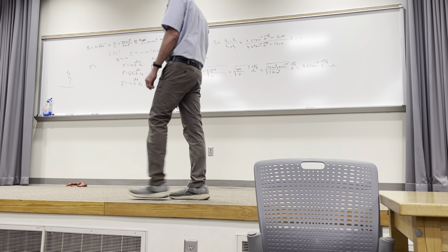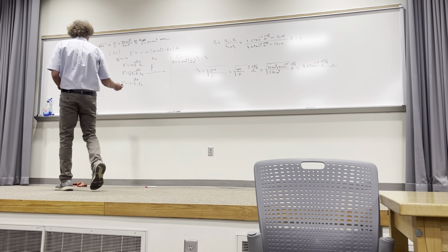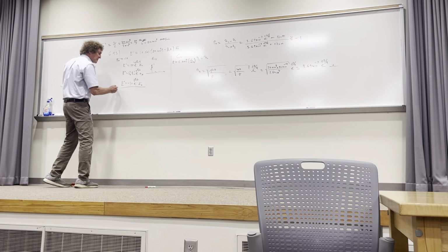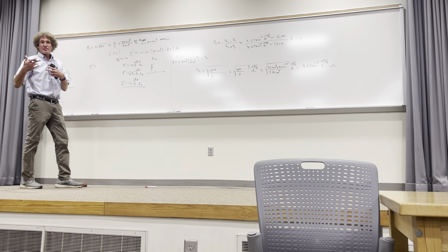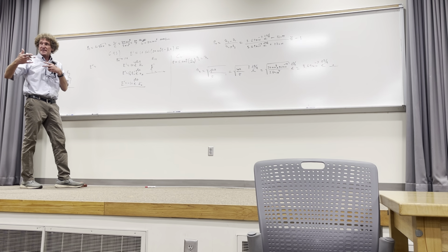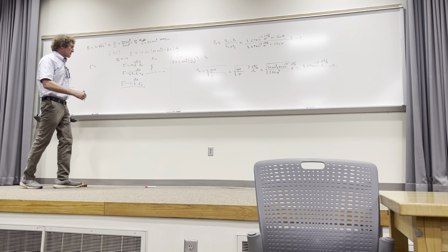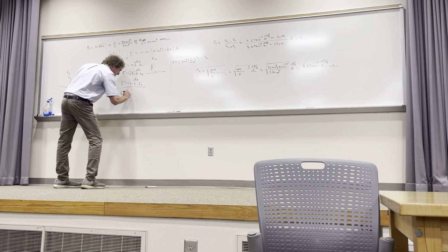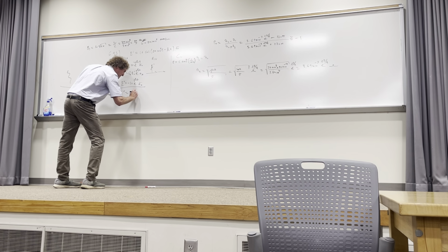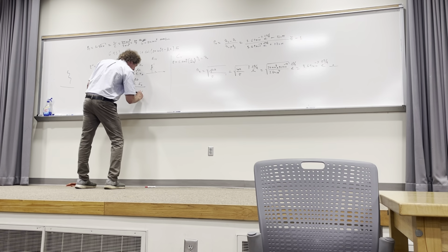All right, if we want it in the time domain, how would we do it? That's the phasor domain, right? What do we do if we want time? Plug it in. Take that times e to the j omega t and take the real part, correct? That's the technical way of doing it. But from the past, really what's going to happen is you're going to take that magnitude -10, and then it's going to be cosine of omega t.